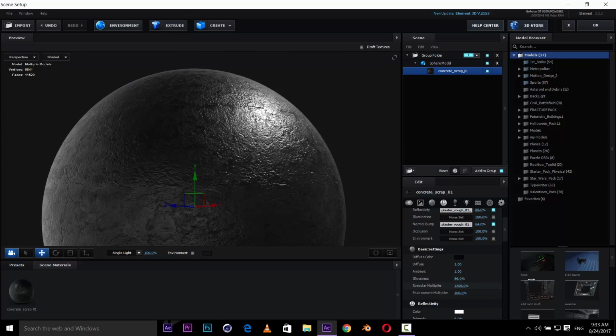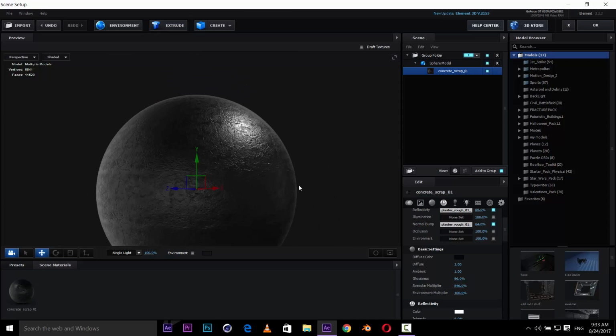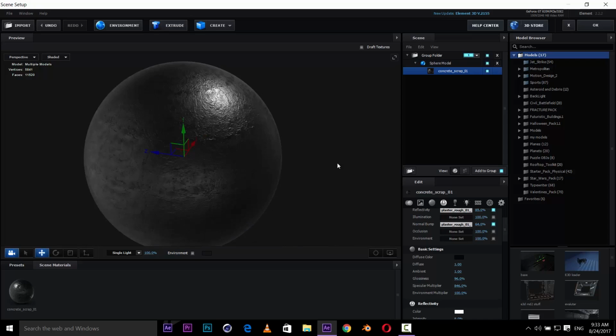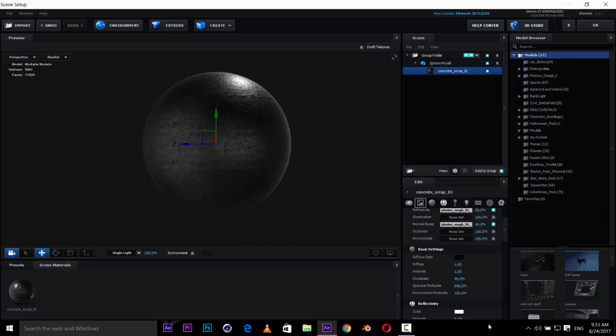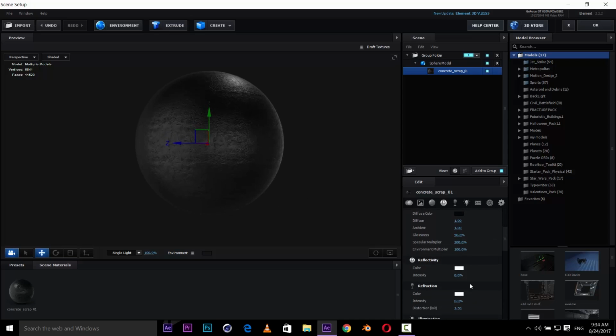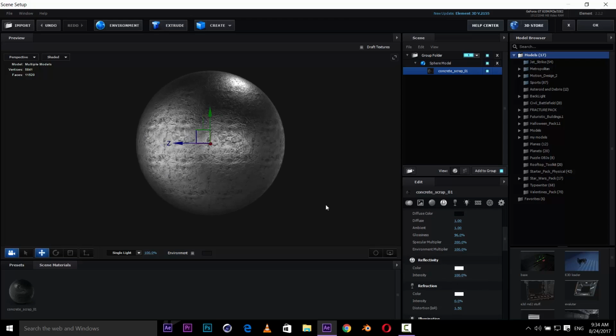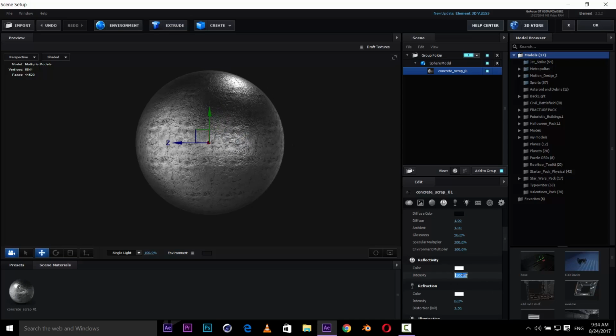You can also increase or decrease it if you want to make a very highlighted part in your scene, just like this one. So maybe put 200, and we can also change it later. So this is now good. And one more setting is reflectivity. We can also increase or decrease it. This time I'm going to put 25, and the material is black, good, fine.